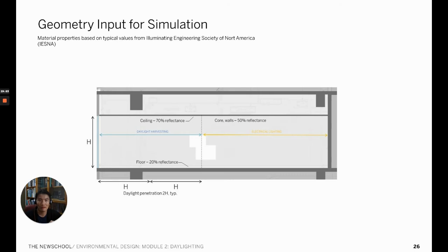Based on the setting, each surface will reflect light around in a different manner, affecting the overall distribution of the incoming light. Usually every ceiling material is designed with white or reflective material to bounce rays deep into the interior space.